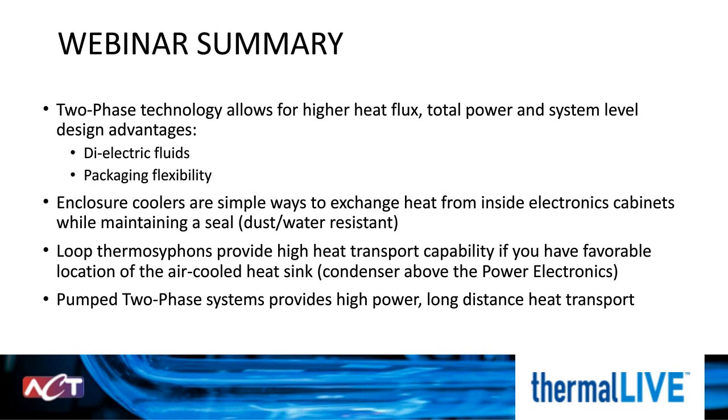The ACT enclosure coolers are a simple way to exchange heat from inside the electronics cabinet while still maintaining that dust and water-resistant feel. The loop thermosiphon provides that high heat transport capability, given the location of the heatsink is gravitationally above the power electronics. And finally, pump two-phase, which offers the high power operation, transfers the heat long distances, and supports flexibility in the design.